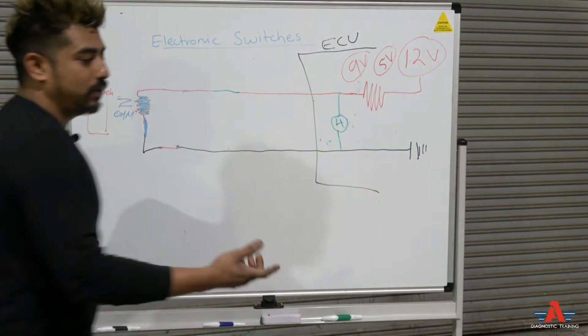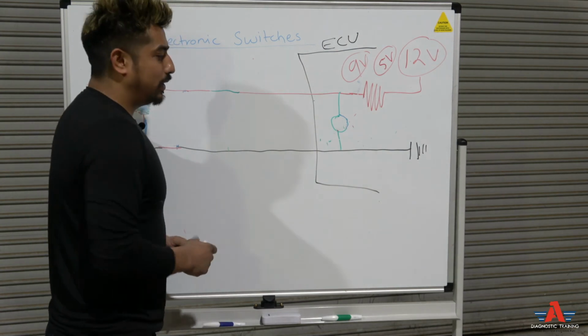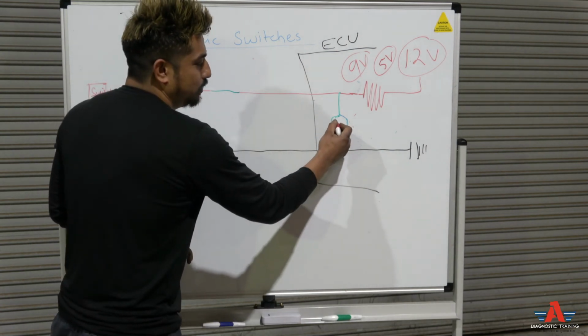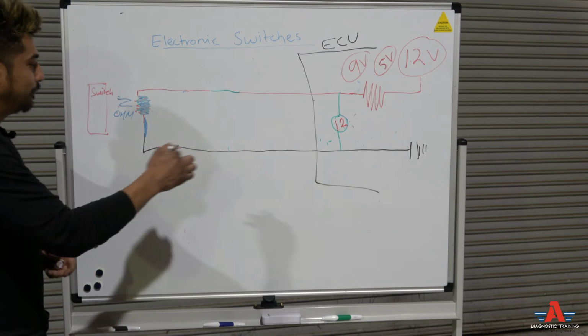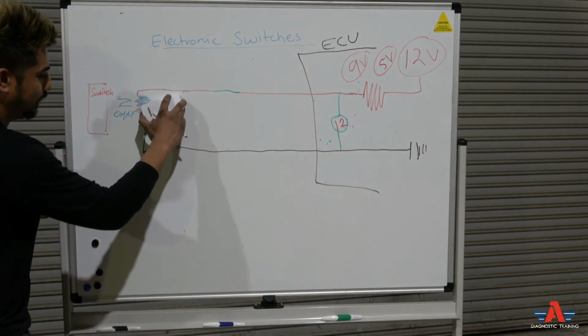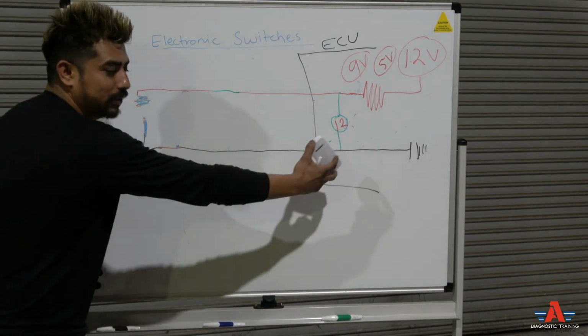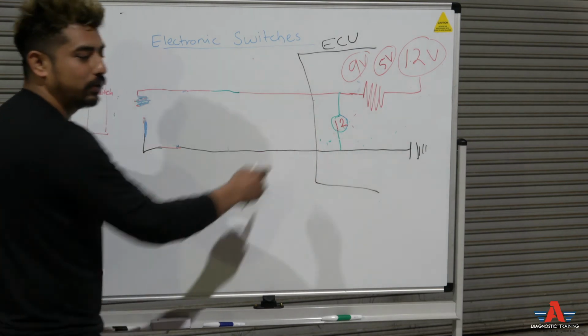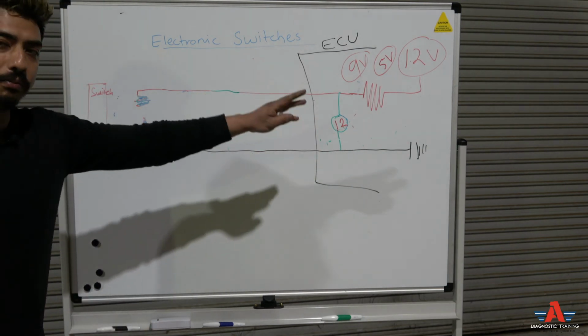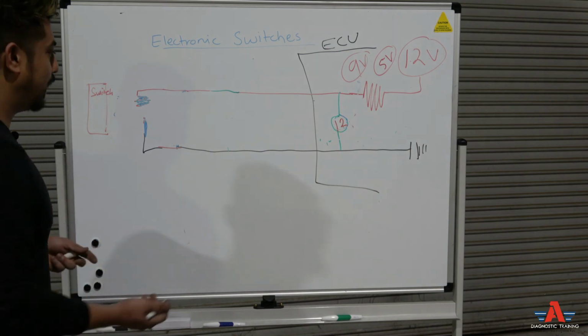All right, let's say you got the same fault code. Like we said, we had an open, right? It was showing 12 volt at the sensing circuit, and our resistor was bad. Right here, our resistor was bad, the switch was bad, so it was never making a path to ground. That's why it was seeing full voltage at the sensing circuit. Computer gave us a fault, battery shorted to battery, the switch is shorted to battery.